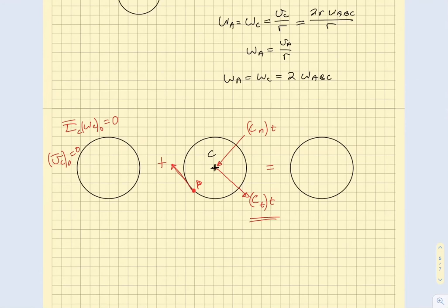multiplied by the time. I'm also going to have the force having to do with the contact to gear B, right? So since we already used C here, we can call this point D, or maybe just call it P, a point of contact here. And then there's going to be some force, and we'll just call it a general force that has to do with the contact. And since we know it's going to be rotating in this direction, I'm going to draw it to the up to the top left. So we'll say some force multiplied by the time there.